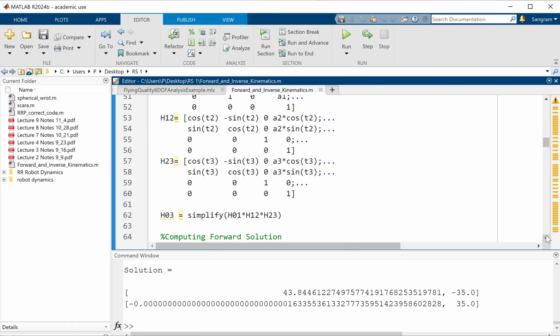What is the coordinate system Dobot is using? If you look at the Dobot map, Dobot uses the right-hand coordinate system. X for Dobot, Y for Dobot is defined there. So it could be different in comparison with the X's and Y's that I have defined here. It means your X, E and Y, E could be flipped. So make sure that your coordinate system is consistent, your link lengths are consistent, and you would get the correct answer. Everyone understood this?